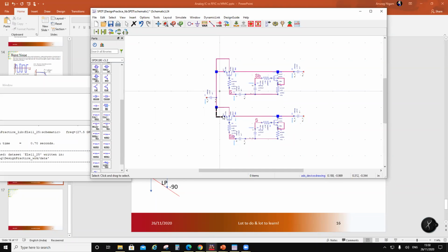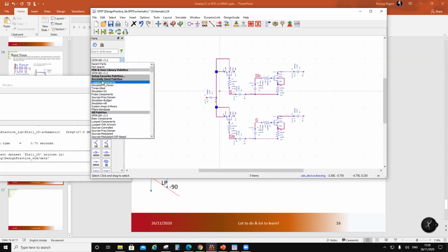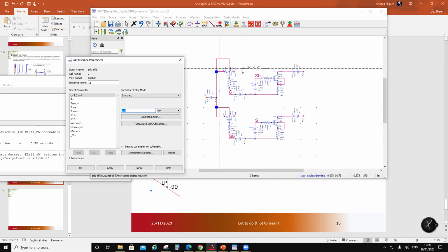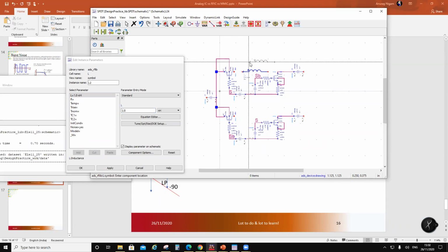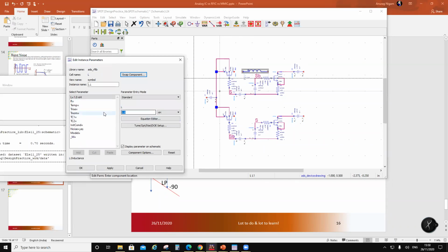Anyways, so now what people will do is put an inductor across these devices and try to anti-resonate this out. Now that makes the switch a narrow band switch. Okay, another thing is, to improve insertion loss, I can insert a certain inductance here. Okay, a small inductance which will be a trace of line only. So let's say I put 20 picohenry over here. So go to lumped components, and I'm going to put here a 20 picohenry.